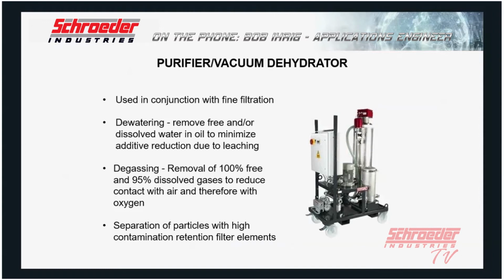One way of achieving all of those conditioning points is with a vacuum dehydrator. We can dewater, degas, and have particulate filtration on one unit. So that's certainly an option for varnish mitigation applications.